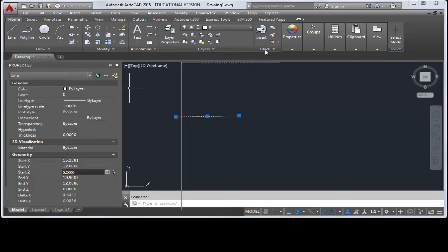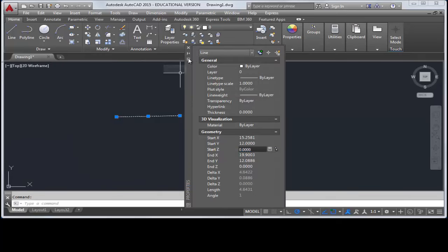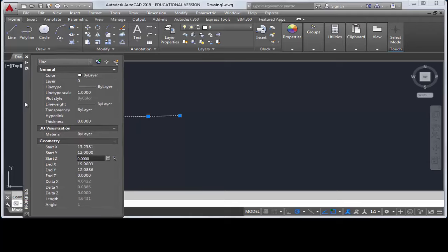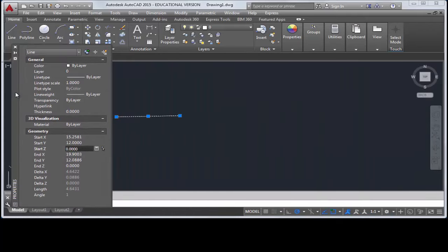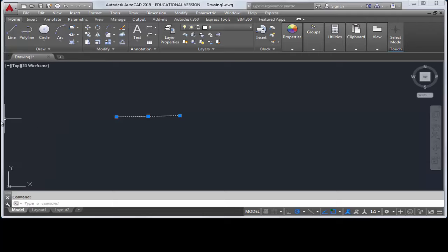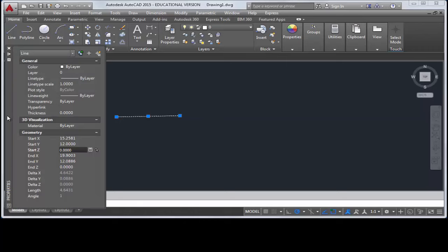So to avoid having that happen, if you go into the Properties of the Properties window, unselect Allow Docking, and that way you can move it any place you want and it won't take up the screen. The other thing you might consider doing is having it auto hide. If I click on this tool, then my properties will only expand when I move my cursor near it.